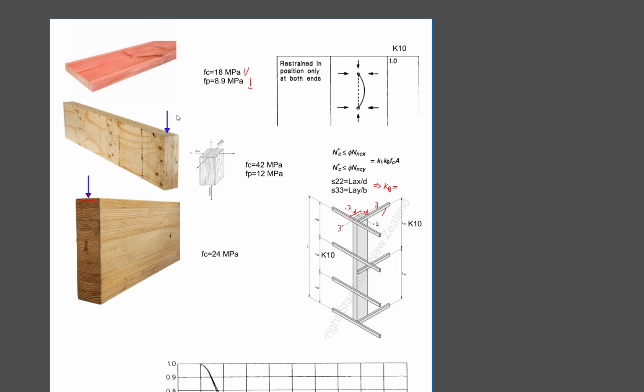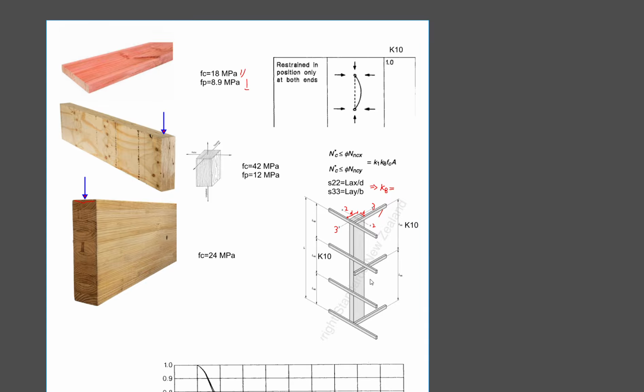So, design a column in axial compression. It takes a little bit of thought. My first take, when I'm looking at my columns, is: first of all, what are the boundary conditions? What are the restraints to my columns?